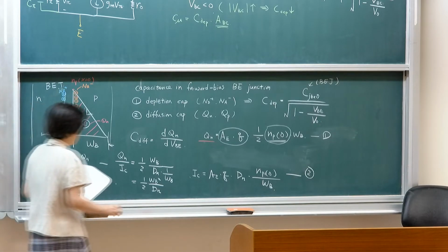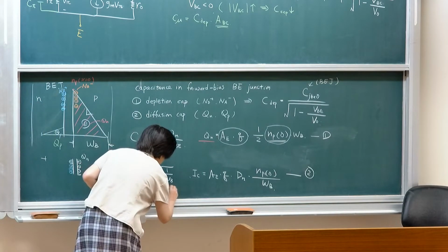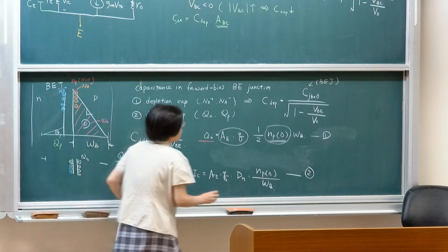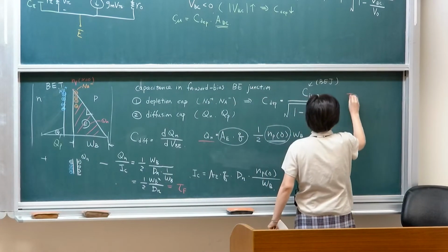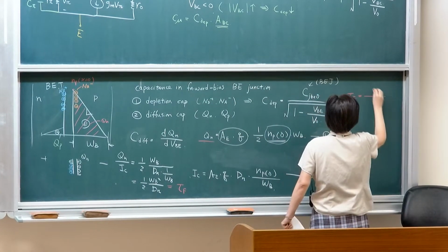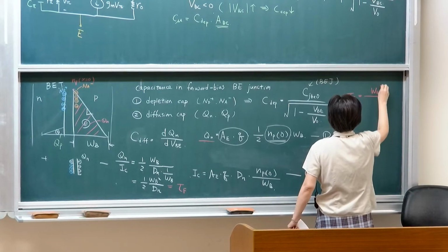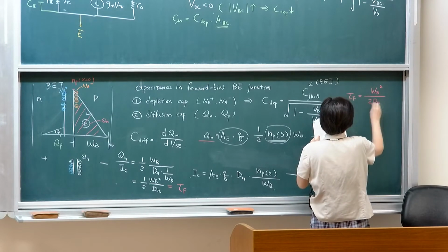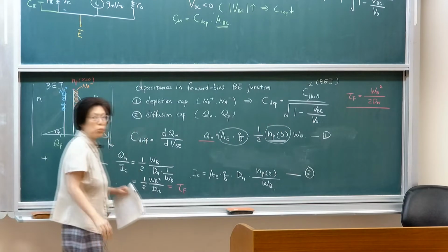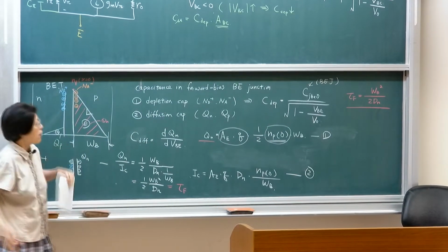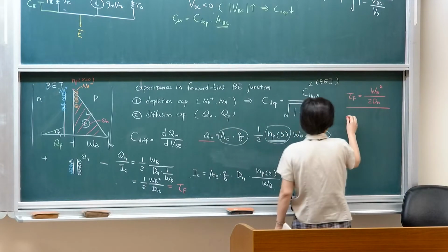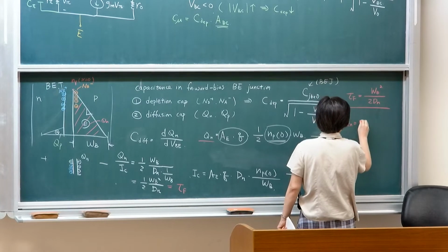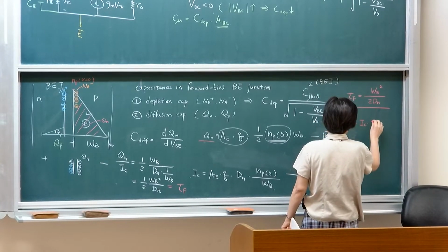This term is in units of time, so it's called the time constant tau f. Tau f is determined by the base width, which is the distance between the two n regions, how far the minority carrier travels, and then we get our final result, where Qn equals IC times tau f.